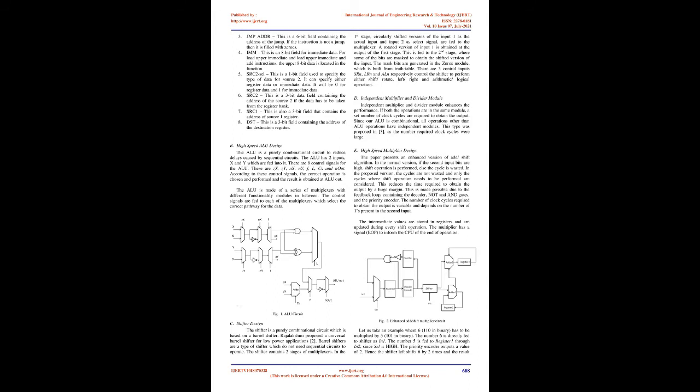C. Shifter design. The shifter is a purely combinational circuit which is based on a barrel shifter. Rajalakshmi proposed a universal barrel shifter for low-power applications too. Barrel shifters are a type of shifter which do not need sequential circuits to operate. The shifter contains 2 stages of multiplexers. In the first stage, circularly shifted versions of the input 1 as the actual input and input 2 as select signal are fed to the multiplexer. A rotated version of input 1 is obtained at the output of the first stage.